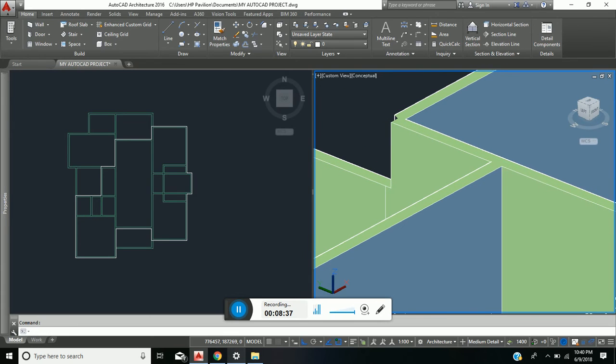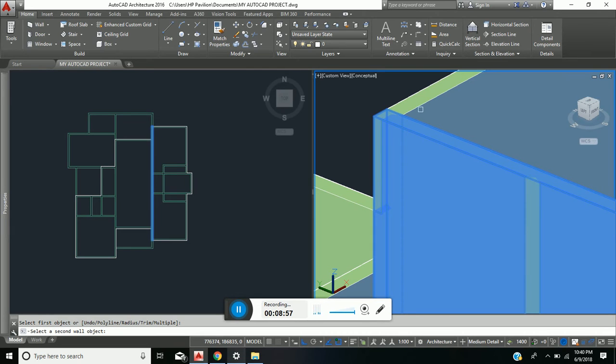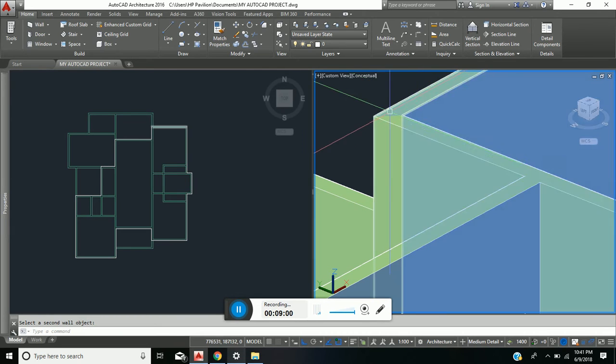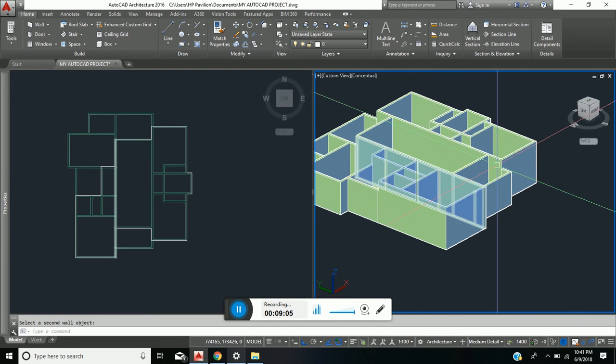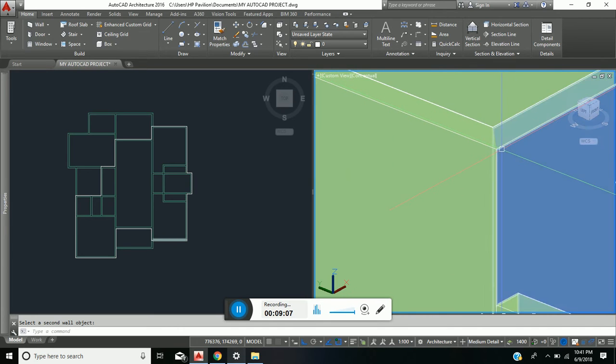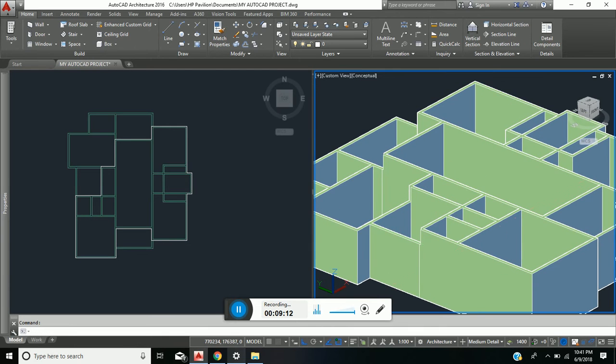And for those corners, all that is necessary is just to do a fillet between those walls to fix that corner right back up. So let's do a fillet, ensuring that you are filleting at a radius of 0. I'm going to be filleting this wall with this wall. Notice the corner cleans up nicely for you. So wherever the walls are broken, if you zoom in and you realize that those corners are damaged, then you could just patch those walls quite easily.